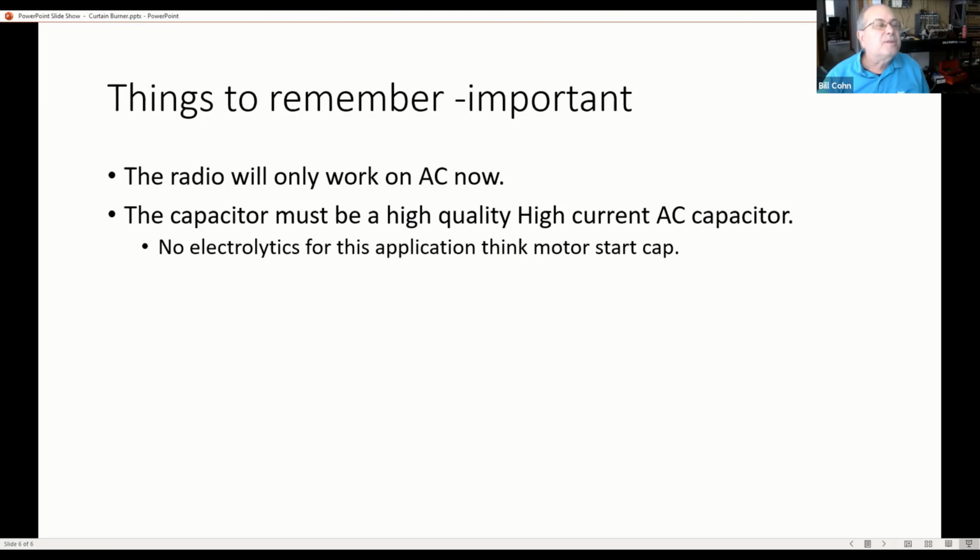Yeah. So, Bill, what do I do with that box of diodes I have? Well, you use them for rectifiers. Just don't use them to drop the filament voltage. Okay. Got to replace all those selenium rectifiers you got. I'm not sure I even have one. Selenium rectifiers? I don't think I have a radio with one in it. No, the radios you have are all too old. Yeah. I have more in the garage, though. If you got anything from the 50s, any of those AC/DC AM/FM radios, they all had selenium rectifiers. Yeah, I don't own a single one.